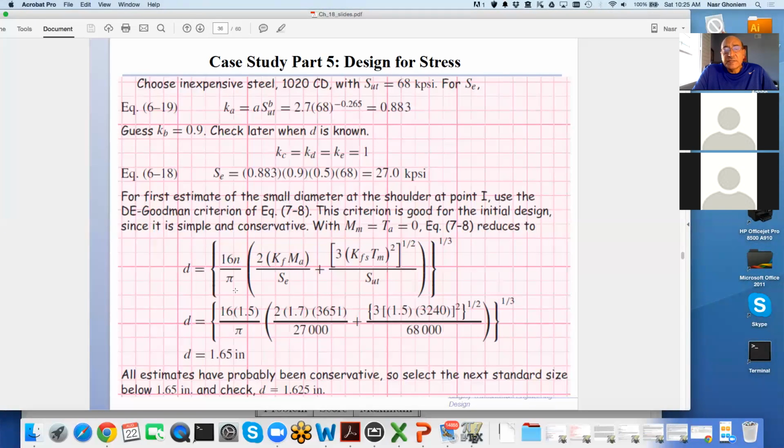It's a fourth-derivative equation from the forces, and then we integrate it to get the deflection. But in reality, when you have various thicknesses for the shaft, that is done numerically, and I have a computer program that you could use to do that in design calculations.